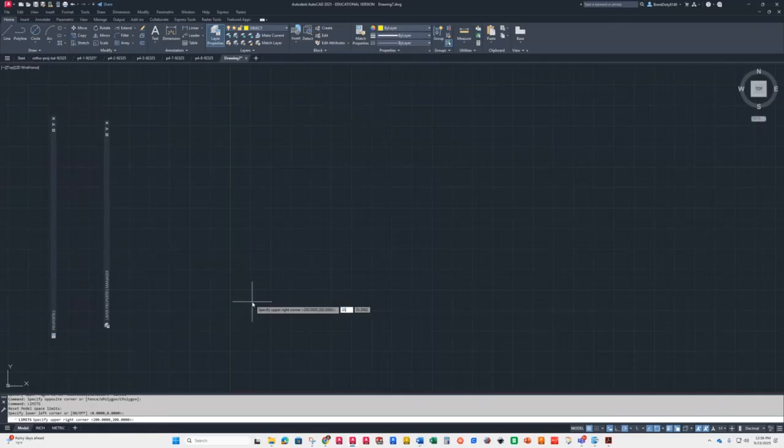So I just type in 200,200 and hit enter. And then, like I said, just do a zoom extents or zoom all, and then it'll get you out. Z enter, E enter, and now you're ready to draw.